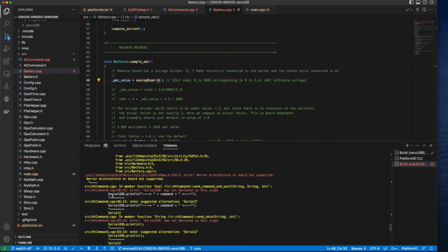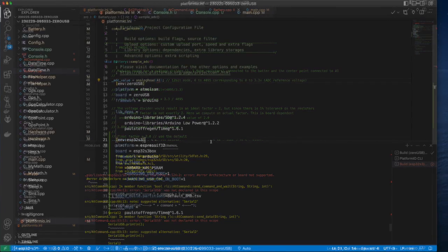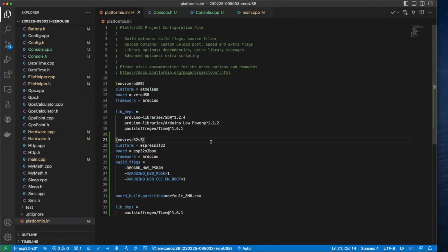The end goal with this is to have a set of code where I can swap boards in and out. So the first bit of refactoring we're going to take care of is abstracting away the board-specific implementations for how you write to the console. The naming, for example, was Serial USB for the Maduino board, and the implementation was named Serial on the ESP32 board. We use a limited number of features for each of those implementations, and luckily for us, the features we use have the same syntax, so we can easily write an abstraction around these implementations.